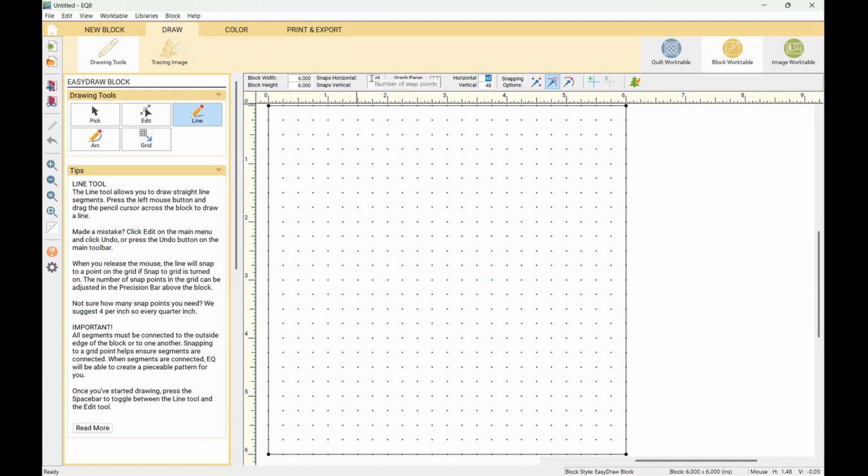So when I say turning on your snaps and turning off your snaps, I am referring to the snap options. You will find that you use snap options a lot when you are working in designing your blocks. And I have to do this myself, when you want to try and remember which snap is what, you can roll over that option and it gives you a description.